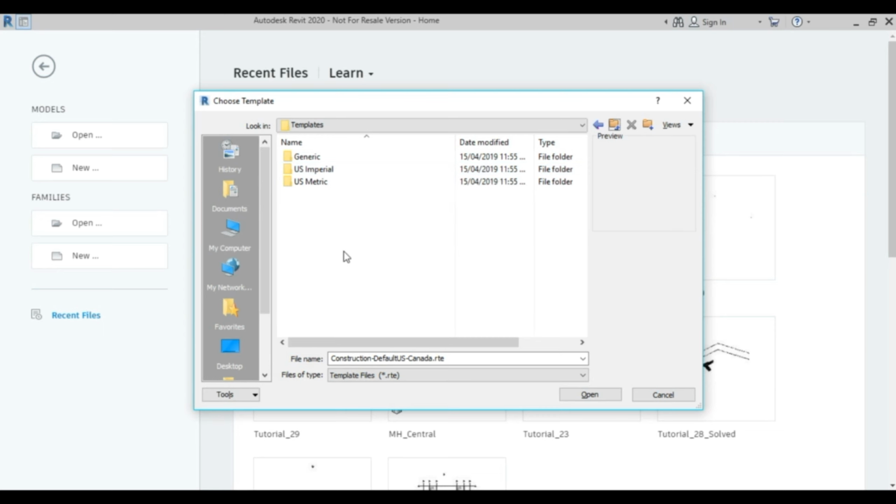One of the very important issues is that if you didn't interfere and left the installation using the default settings, Revit will install two contents for you, which are US Metric and US Imperial. By making US Imperial the default, once you create a new project, the US Imperial will be the one shown for you. I asked Revit to make US Metric my default.